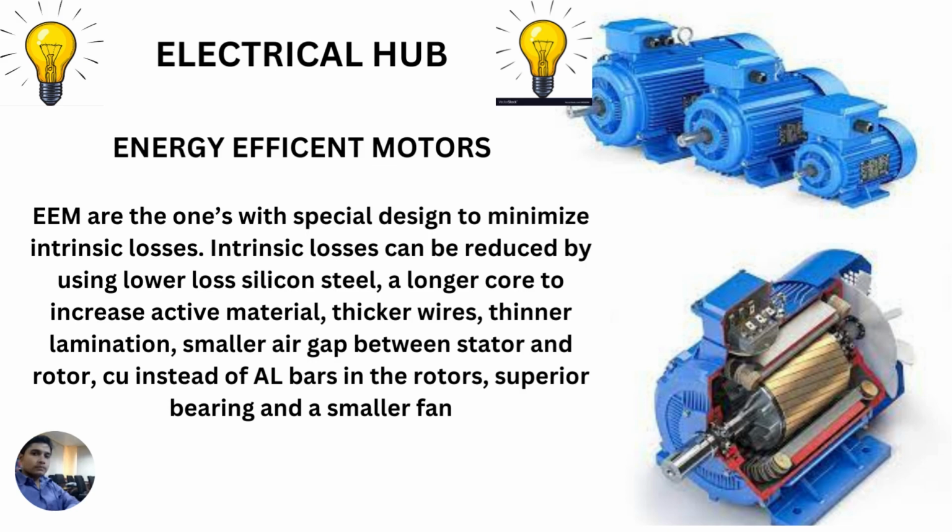Energy efficient motors are the ones with a special design to minimize intrinsic losses. How can the intrinsic losses be reduced? It can be reduced by using lower loss silicon steel, a longer core to increase the active material, thicker wires to increase the cross-sectional area, thinner lamination, a smaller air gap between the stator and the rotor, copper instead of aluminum bars in the rotor, superior bearings, and a smaller fan.